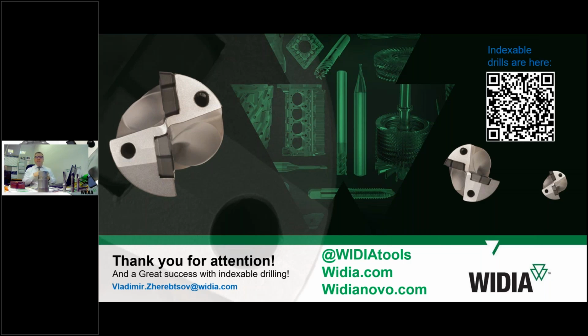I mean, to check the reliability of the chip evacuation process, because usually if the tool is assembled from a combination of carbide and steel, it's more critical to work with a coolant. It can also overheat inside.